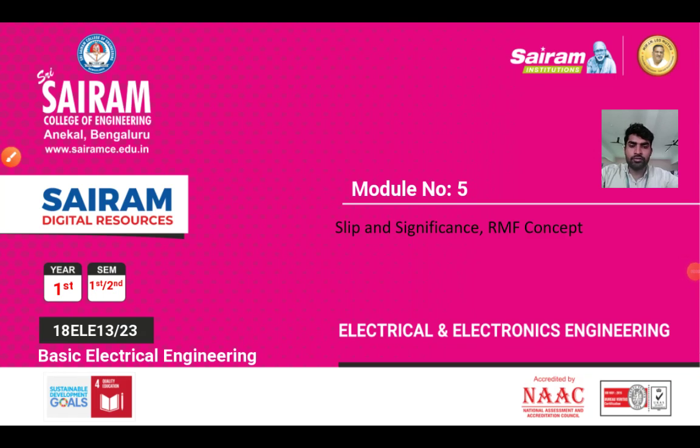Morning students, in this video we will discuss slip and its significance and rotating magnetic field concepts. So what is RMF? Rotating magnetic field. How will you get that rotating magnetic field? Once you give power supply to the induction motor. This rotating magnetic field concept is related to the stator, and the speed of that rotating magnetic field is Ns equal to 120F by P. And slip and significance.